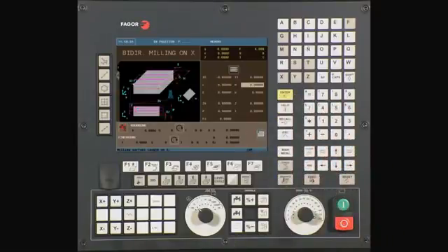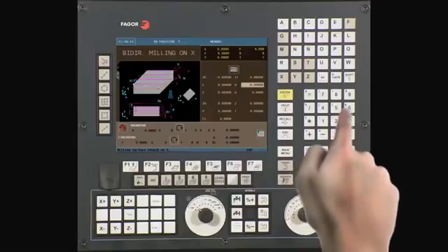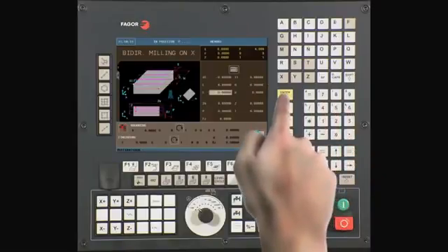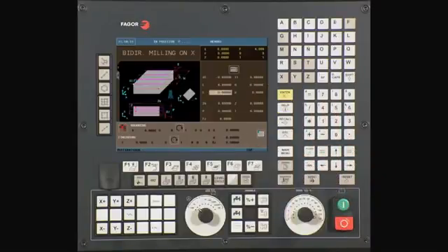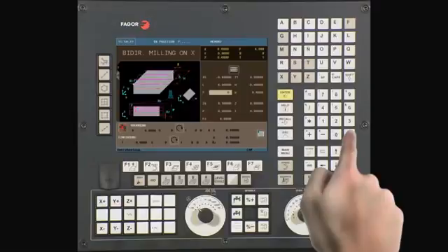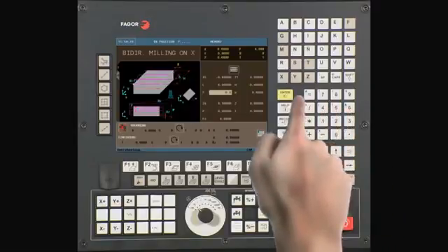H is the length along the part in the Y-axis. According to our drawing, this is minus 6 inches. Type minus 6 and press Enter to continue. E. This is the amount of tool overshoot beyond the program part perimeter edges. In this example, it is 600 thousandths of an inch. Type 0.6 and press Enter to continue.